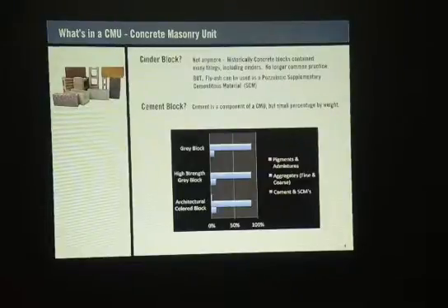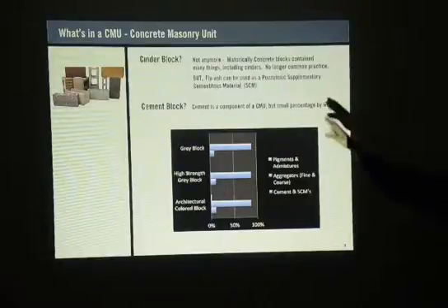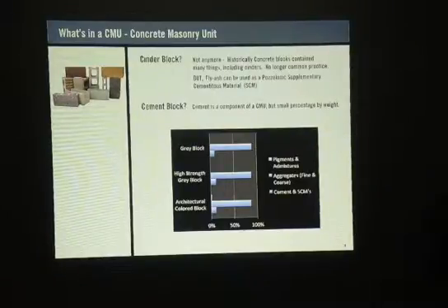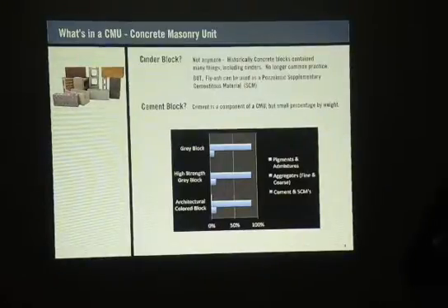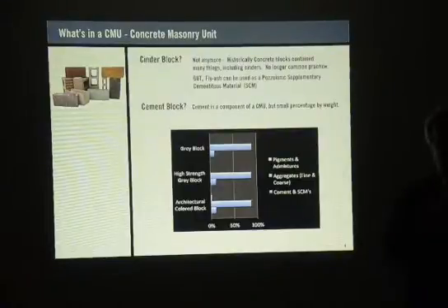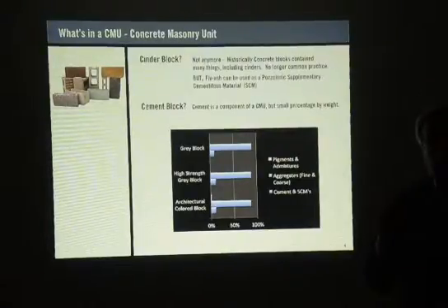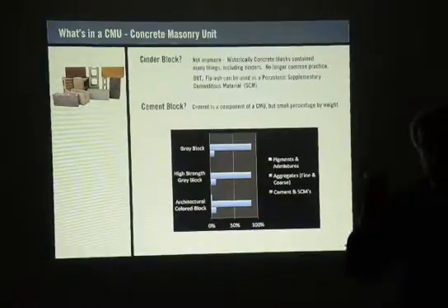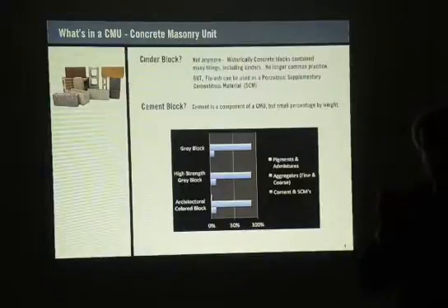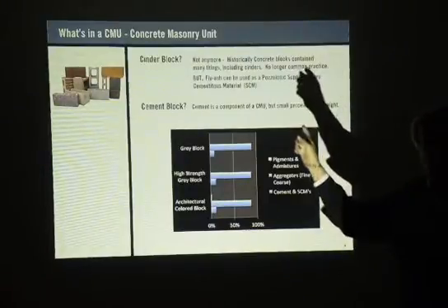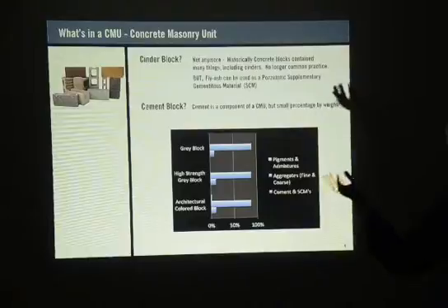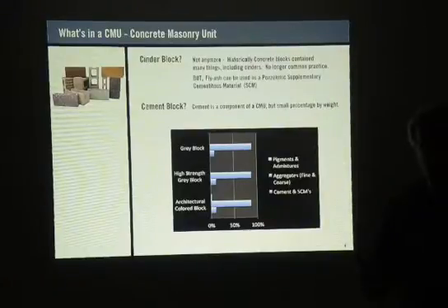Okay, so now this is where one of these slides says it's not used anymore. That's not true. In Southern California especially, and even in Northern California, because of the raw materials availability, there are quarries that are drawn for CMU and for block applications that have cinder in them. What does cinder do, Mike? It lightens the block itself, okay?